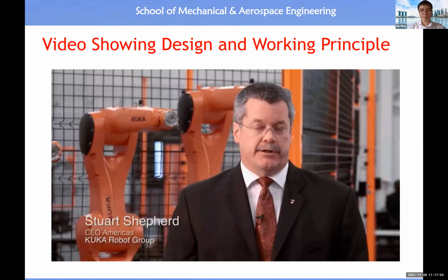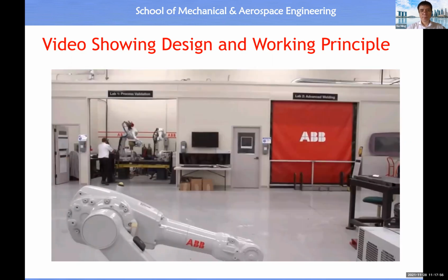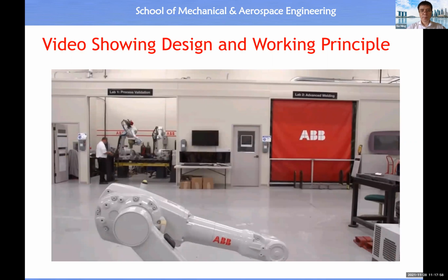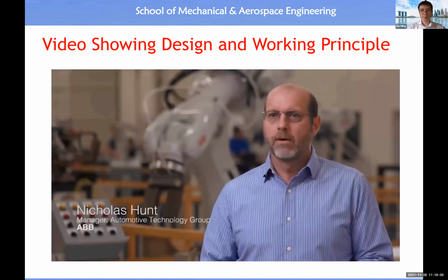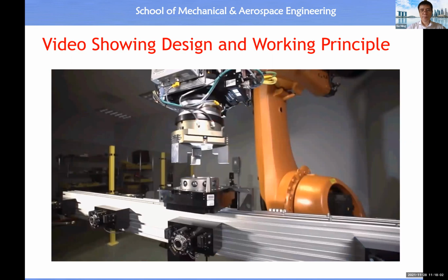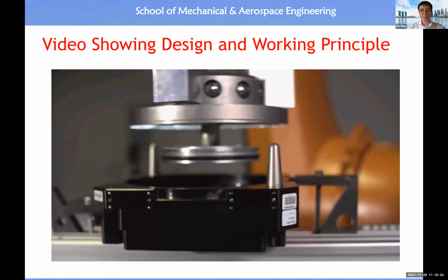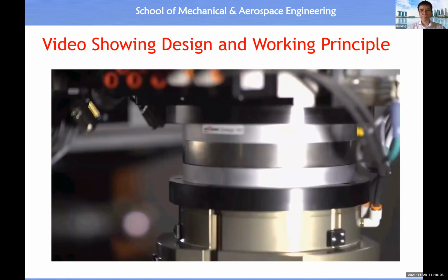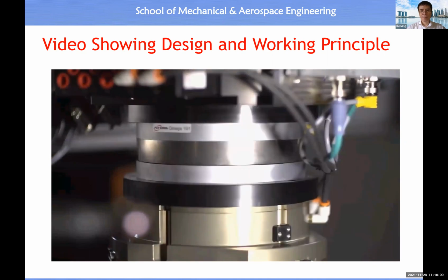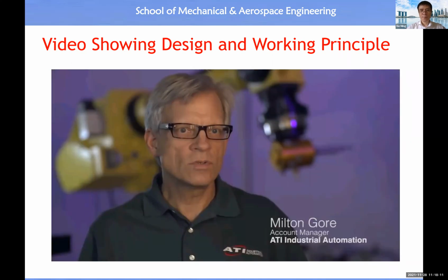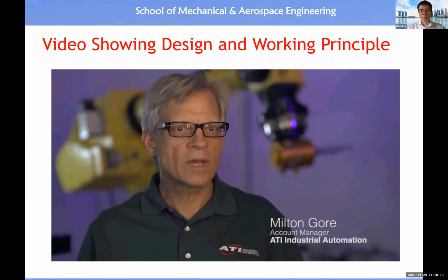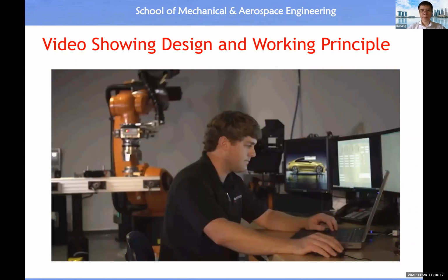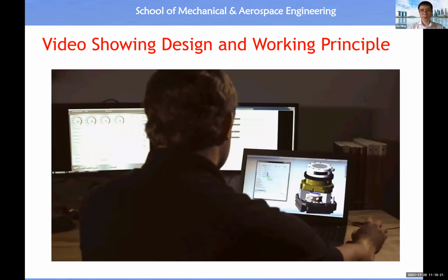One of the things that makes robotics really function is repeatability or precision. What the force torque sensor from ATI gives us is both accuracy and repeatability. The force torque sensor is a device that uses silicon strain gauges and converts mechanical loads into forces and torques, and it measures simultaneously in all 6 axes, force XYZ and torque XYZ.